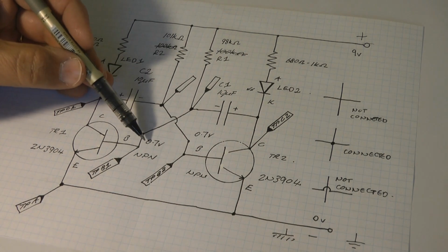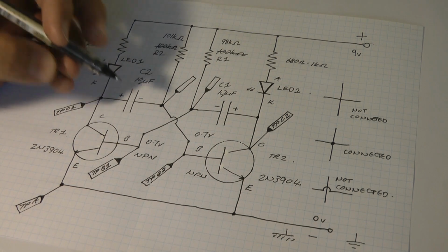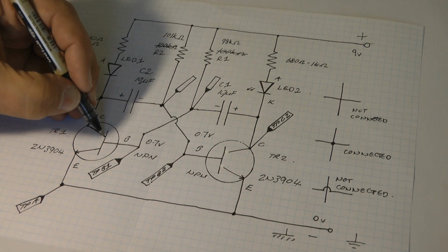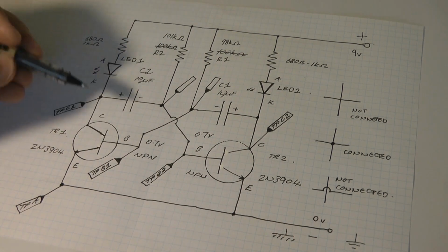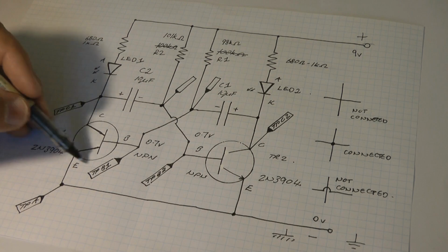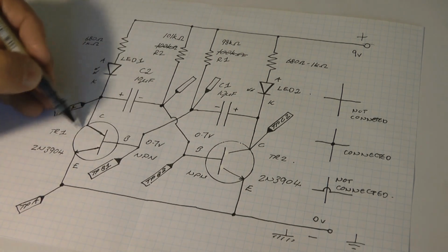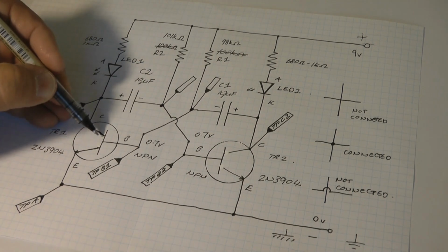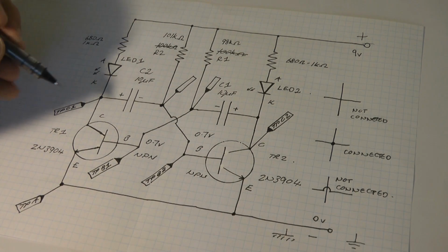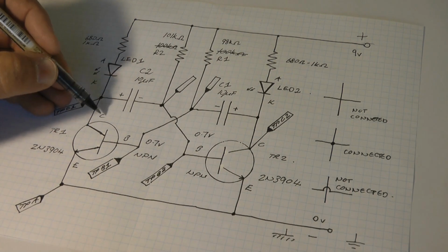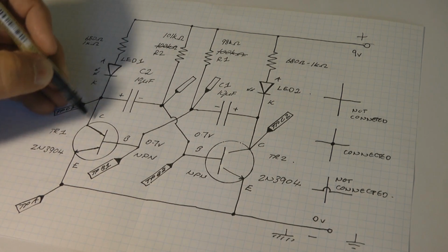But now as the base reaches 0.7 volts and the electronic switch action of the transistor comes into play, in that moment where this transistor is fully biased on, these junctions here would have closed the switch inside of this transistor. It's not a physical switch, it's an electronic switch. And effectively what that means is there's a dead short circuit between the collector and the emitter, and there's current flowing through here.